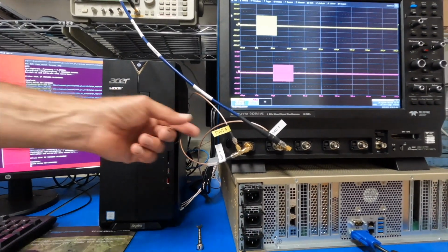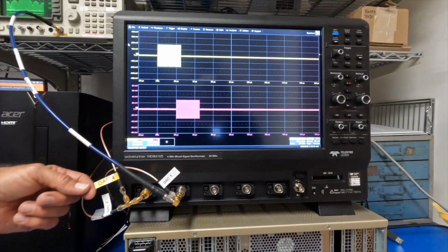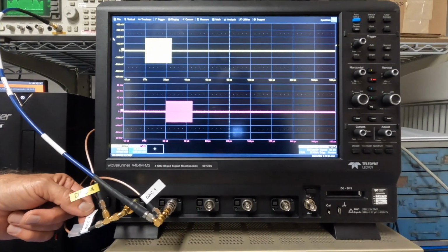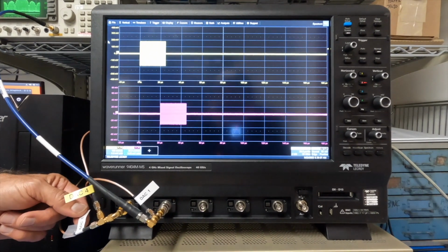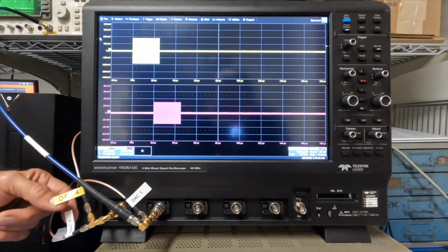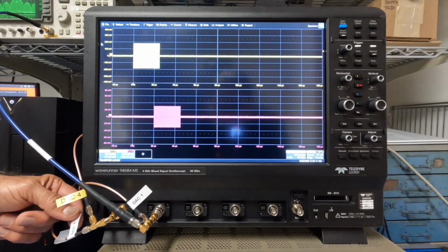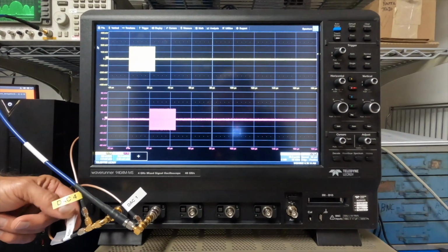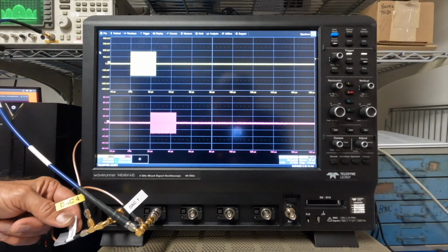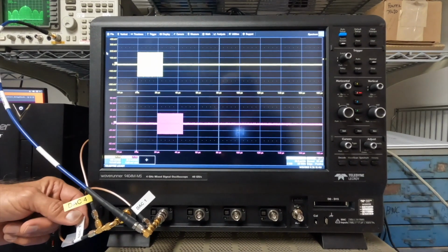So DAC 4 is first feeding the A to D input for channel 1. Our pulse train is going into one of our analog to digital converters, and that's going to be feeding the digital RF memory. It's going to be capturing it, storing it, and playing it back, and we'll show you that feature in a second.